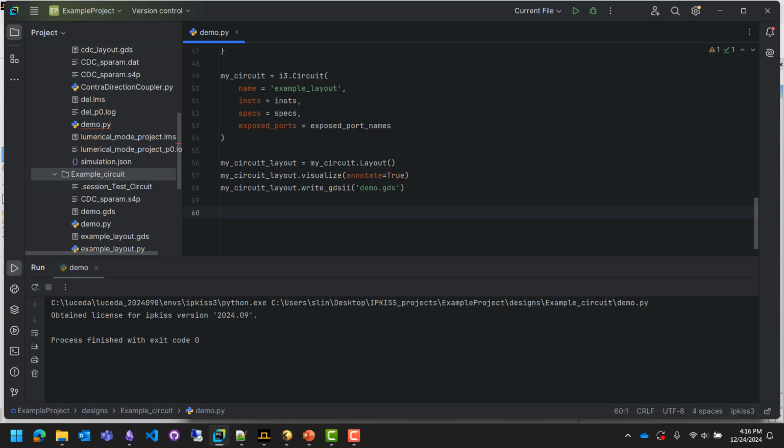And then what I'll do is I'll show the grating coupler's innate response, and then I'll show the contradirectional couplers. And then what we should see on the final plot where we have a circuit model of the whole thing is that we'll see our filter response on top of our grating coupler response.